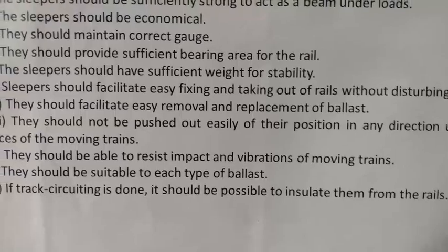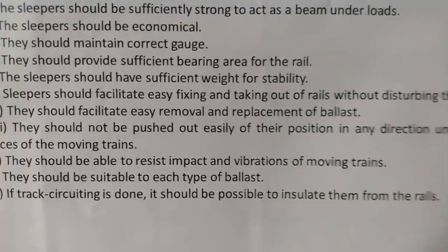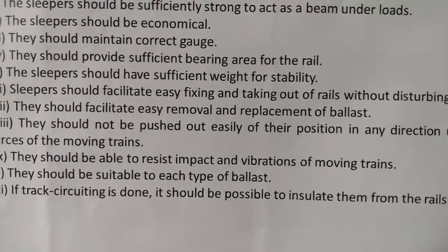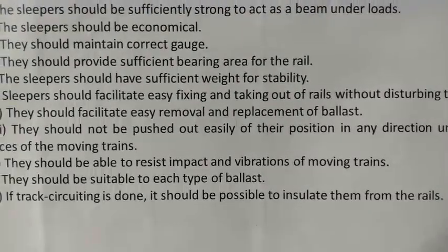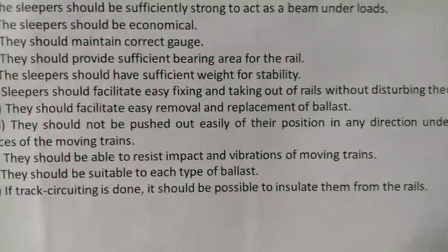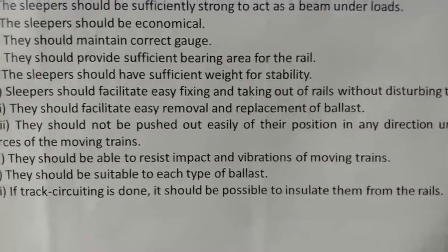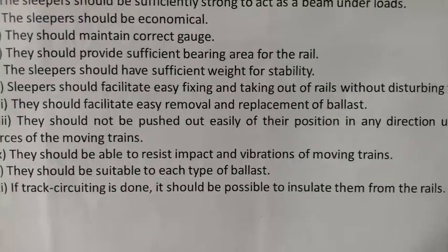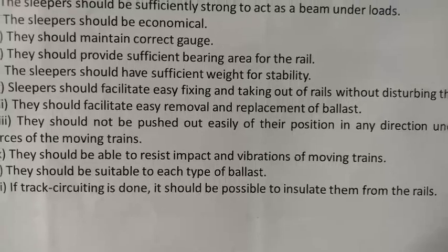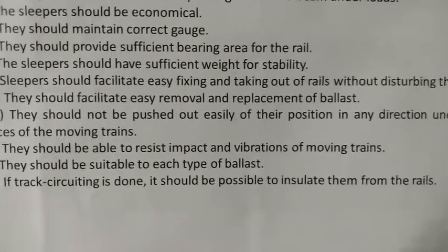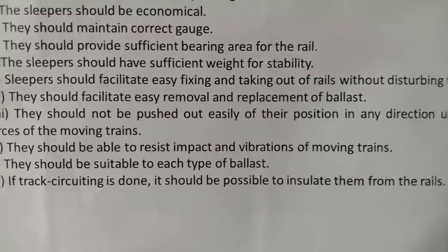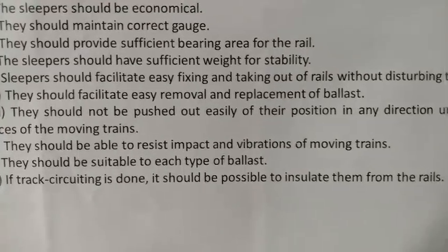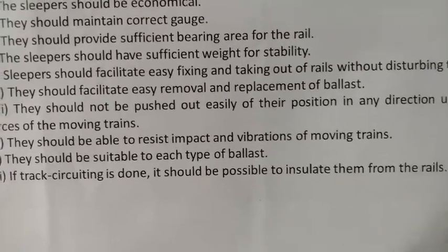For that removal, or the replacement of the ballast whenever it is deteriorated, we have to take out the sleepers first, because the ballast is just beneath the sleeper. I have explained this more clearly in my previous video on the types of sleepers, with a cross section drawing.